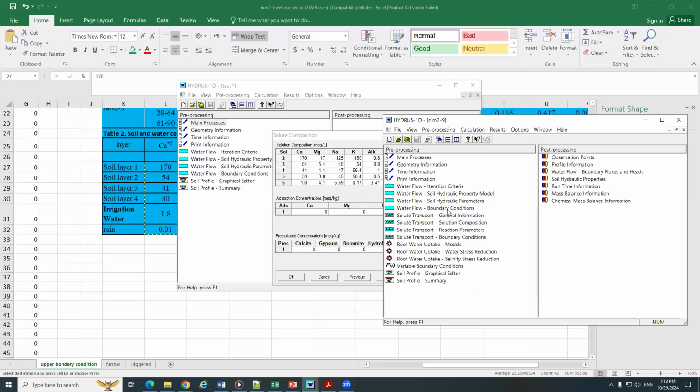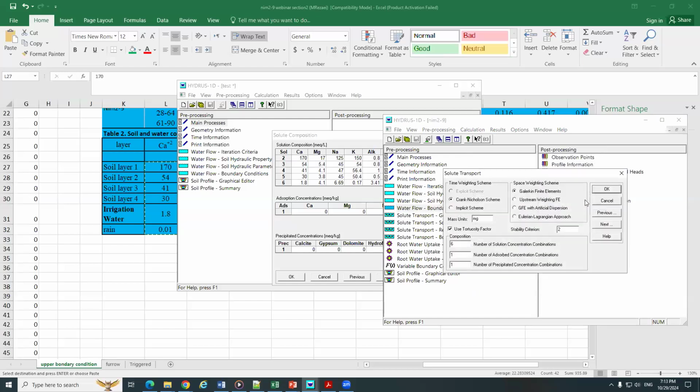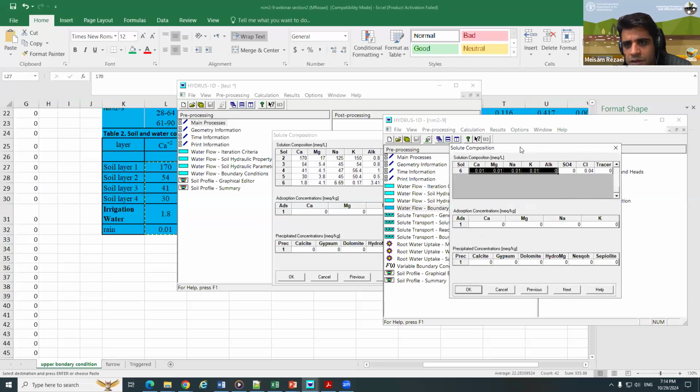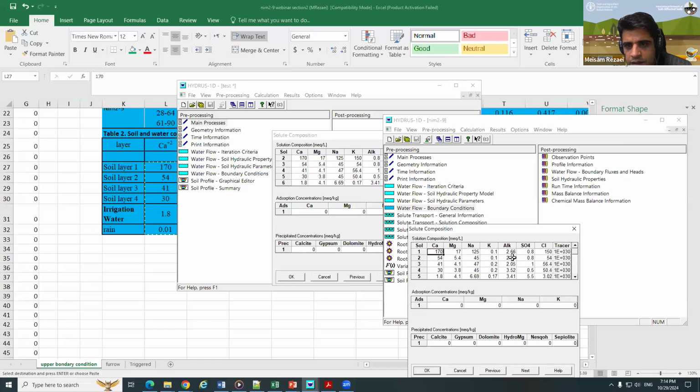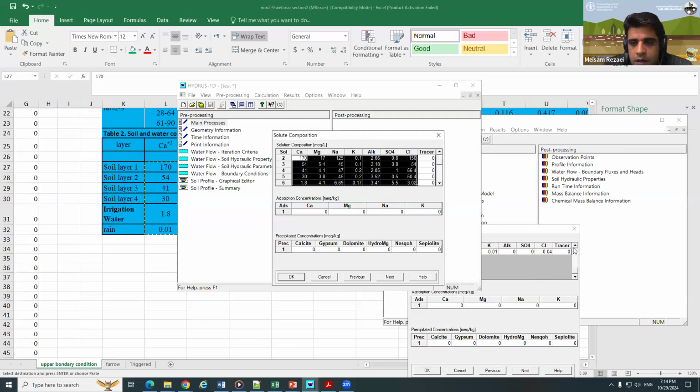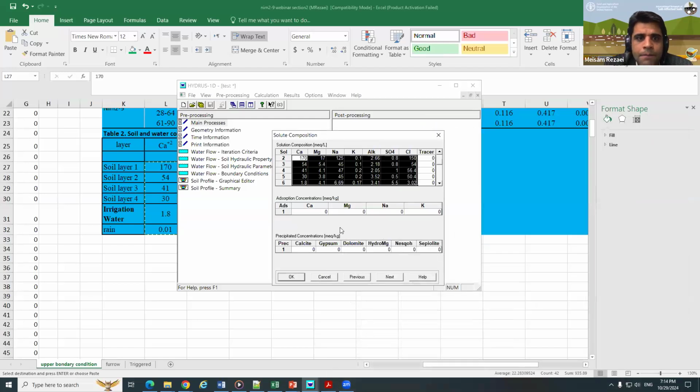And these are available concentrations of cations in soil layers. The available concentrations of cations, actually the composition, is based on the soil saturated paste extract. And for the adsorption, you have to measure the cation exchange capacity, and during the procedure you can measure the exchangeable calcium, exchangeable magnesium, and exchangeable potassium and sodium. Once I don't have the exchangeable data, I push 0.